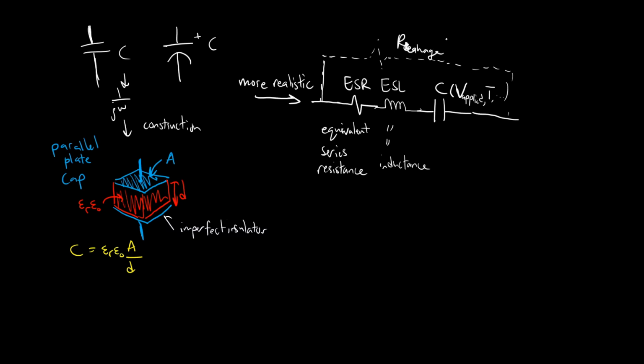And typically for a lot of capacitors, this is a very large resistance. It very closely approximates an open circuit, but it does affect how long the capacitor can store energy when it's disconnected from other things, right? Eventually, this leakage resistance will just bleed off whatever power you're trying to leave in the capacitor. That kind of makes them bad for long-term storage, right?